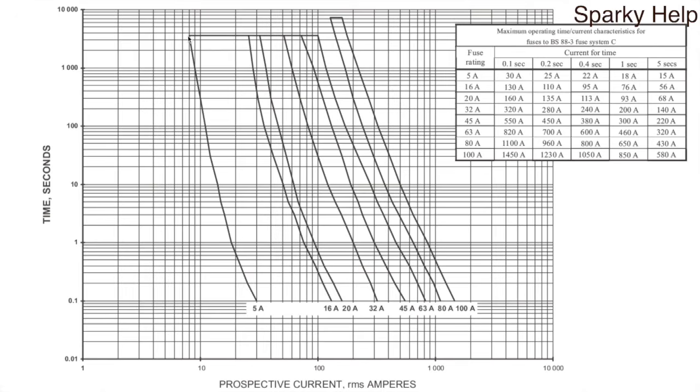So the Ia, if our disconnection time was 1 hour, which clearly it isn't, then the Ia for that device at that particular time would be 8 amps. So that's what it's quite good at. Clearly we don't want a fault to be 8 amps, because it would sit there and hold for an hour, which basically means the place may well burn down. So that's not what we want. And the sort of fault that would cause that would be overload, which we try and design out in the first place. It's quite difficult to use, but it gives us that information.